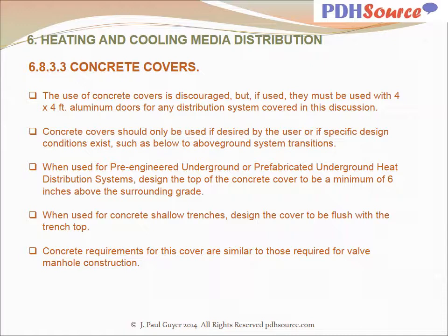When used for pre-engineered underground or prefabricated underground heat distribution systems, design the top of the concrete cover to be a minimum of 6 inches above the surrounding grade. When used for concrete shallow trenches, design the cover to be flush with the trench top. Concrete requirements for this cover are similar to those required for valve manhole construction. Concrete cover shall be provided with details for this cover.